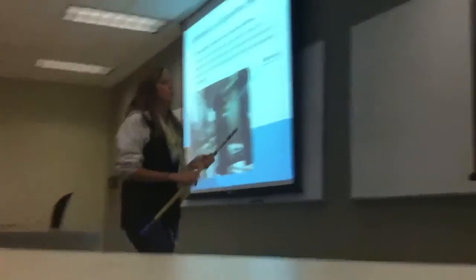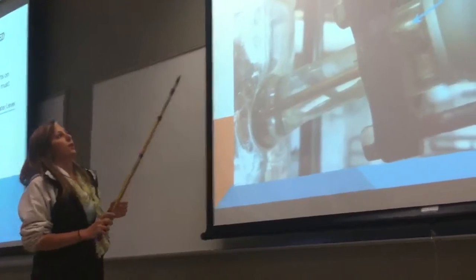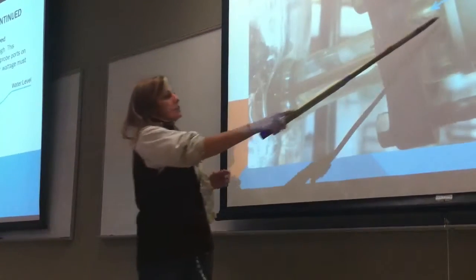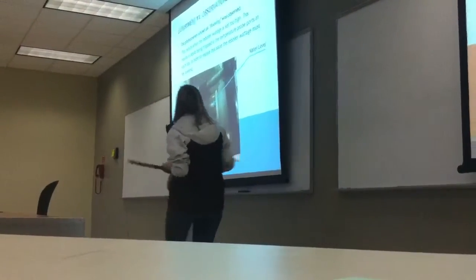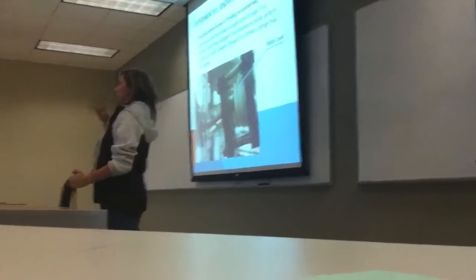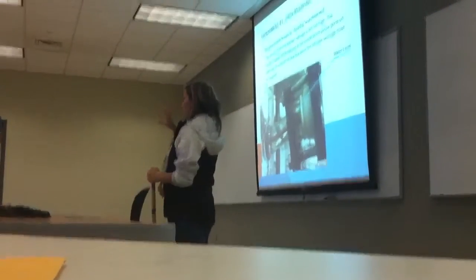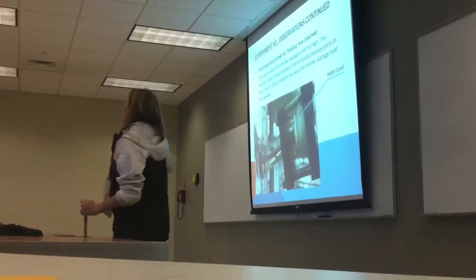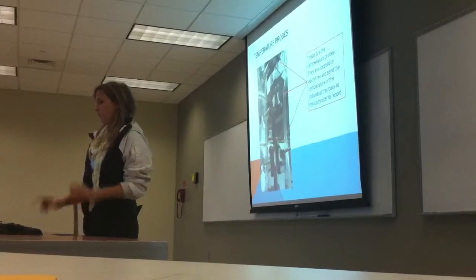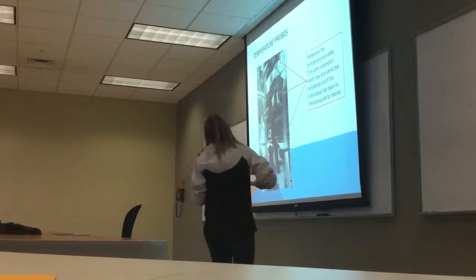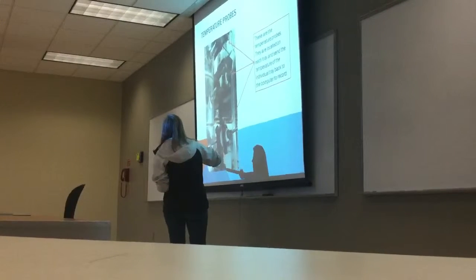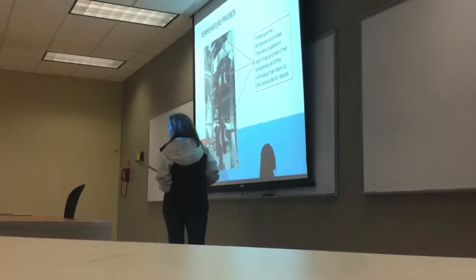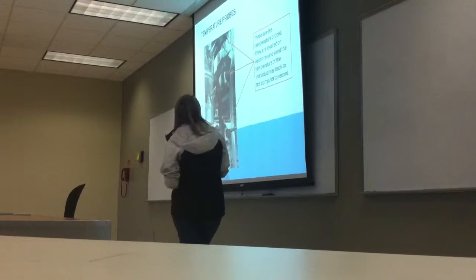And then in most of the experiments, we noticed this phenomenon known as flooding. In this picture, there's the water level line. And this occurs when the wattage is too high, so the liquid gets trapped in these ports, because the vapor is going up too fast. So this is the temperature probes, and this is where in these ports the water gets trapped from where it's bubbling up and the vapor is going up too fast, and the liquid gets trapped in those ports.